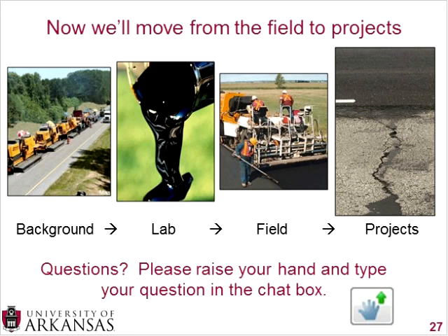But again, it's my perception that HIR should, at the end of the day, be identical to HMA or warm mix asphalt. You won't be able to tell any sort of ride quality difference, and these end parameters like air voids and density really shouldn't change, because at the end of the day you want a typical asphalt concrete surface course in place. So I haven't seen any guidelines for typical ranges or any sort of recommendations, but going out on a little bit of a limb here, I would say it's just the same as what your typical hot mix or warm mix air voids would be.